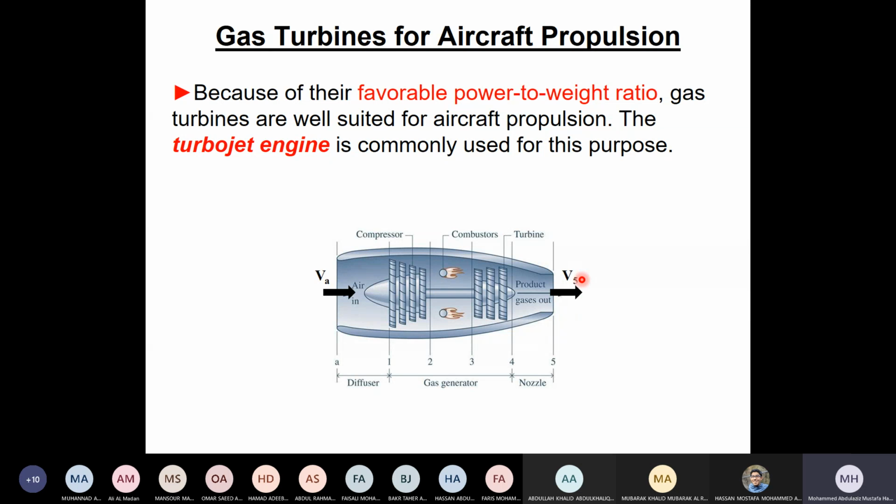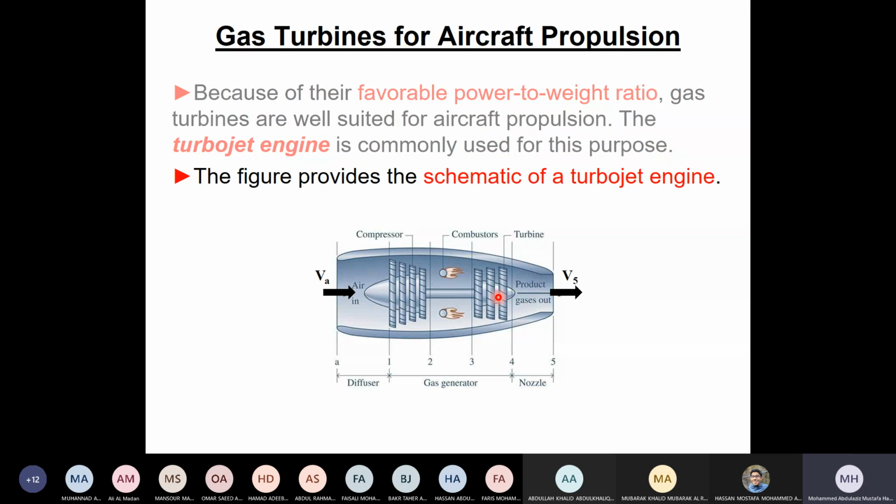The second point is that one feature of this gas turbine is that the turbine only runs the compressor. In the previous part, the stationary gas turbine, part of the turbine work, which you mentioned as 40%, goes to the compressor and 60% goes to the generator. Now we do not have a generator here, and therefore the turbine work is equal to the compressor work. Remember, turbine work is equal to compressor work because this is just a shaft and they are connected together, nothing else. So this has to be satisfied. We will come to that.